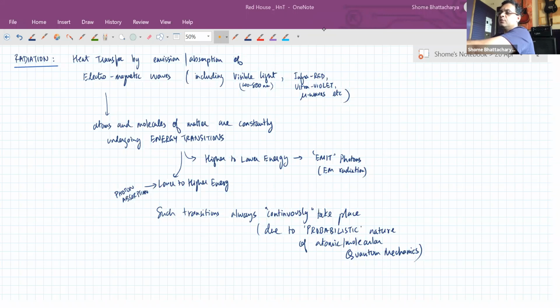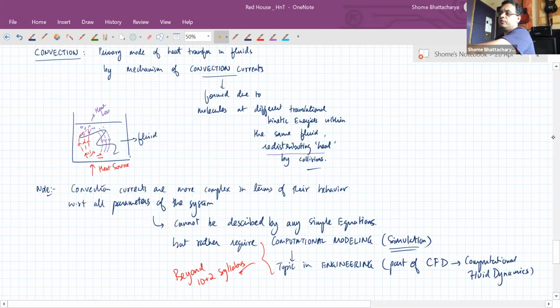No? So anything which is electromagnetic in nature, in wave nature, is part of the electromagnetic spectrum, right from radio waves to gamma radiation. Any electromagnetic wave phenomenon is somewhere in that electromagnetic spectrum, from the highest wavelength, which is of radio waves, to the lowest wavelength on the other side, which is of gamma radiation. Okay, so when we talk about radiation and heat transfer, we're talking about radiation via electromagnetic waves only. So now you understood. The waves emitted or absorbed have to be somewhere in that spectrum of electromagnetic waves.